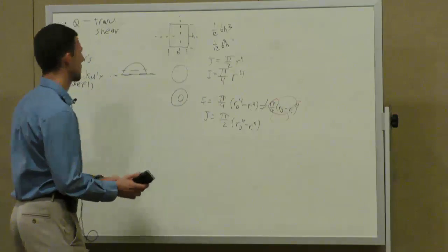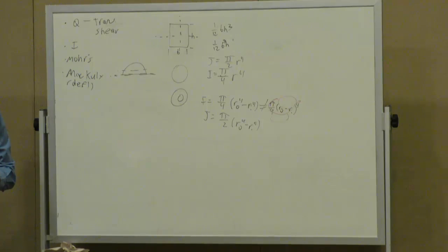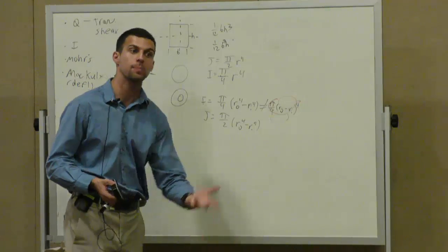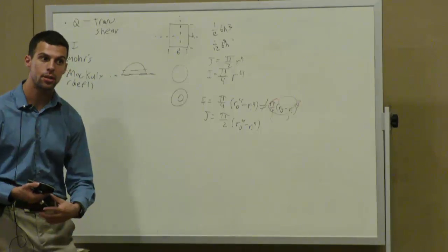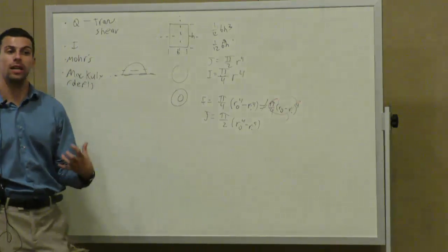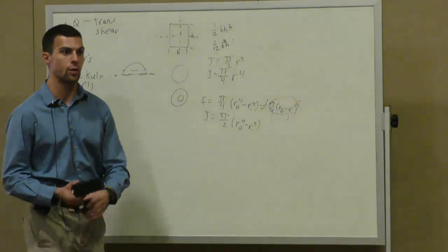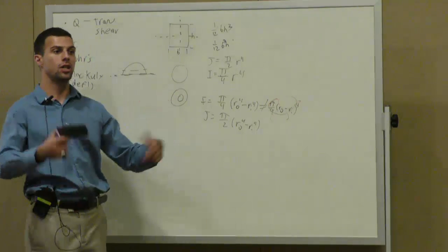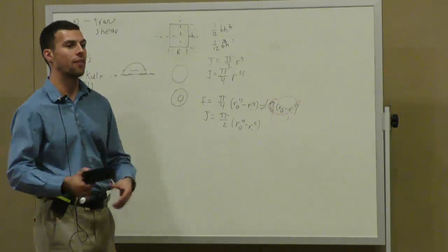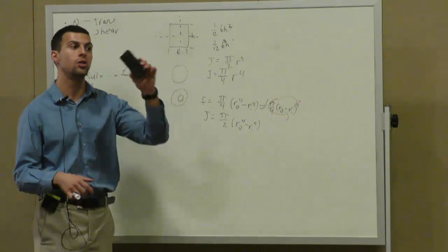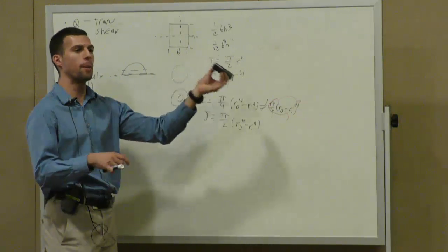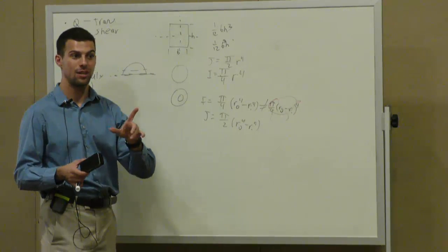All right. So are we now comfortable with I a little bit more? Again, if you were looking at more complex or composite shapes, such as I-beams, I, unlike a y-bar prime, is subject directly to the law of superposition. So in order to establish I's, you just need to add them up. Now the trick is you have to add them up about the correct axis. So you might have to do what? We did a bunch of it in the dynamics session.